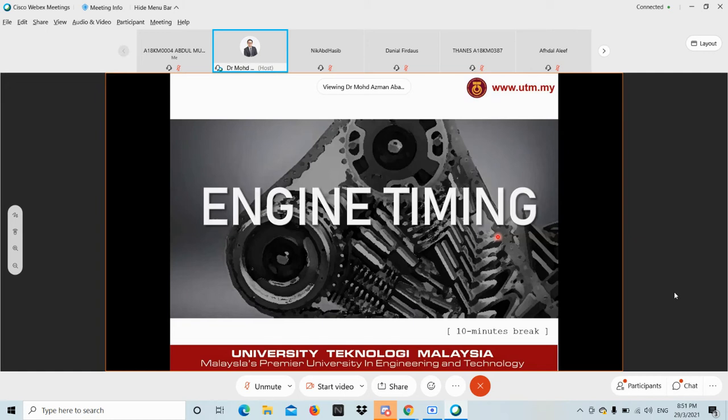When more air goes into the cylinder, then you put a sufficient amount of fuel to cater for how much air goes into the cylinder. So the fuel follows how much air is put into the cylinder. That is the SI engine. So in order to produce more power in the SI engine, all you need to worry about is how much air you can fill into the combustion chamber. That's the basic rule.